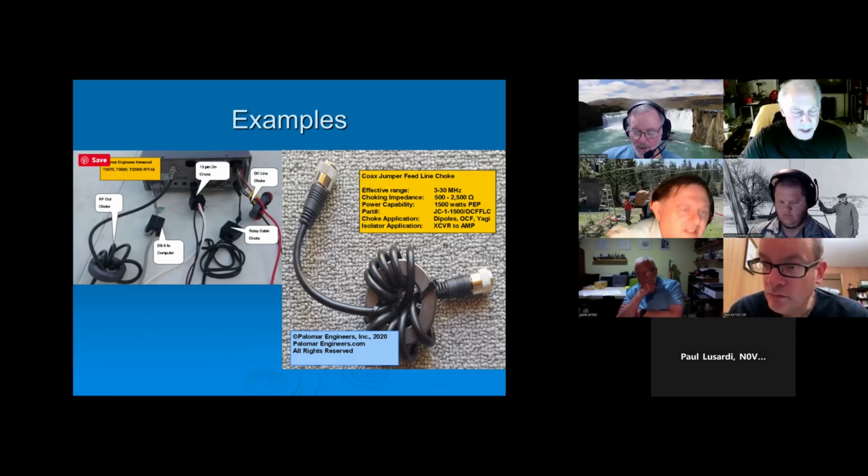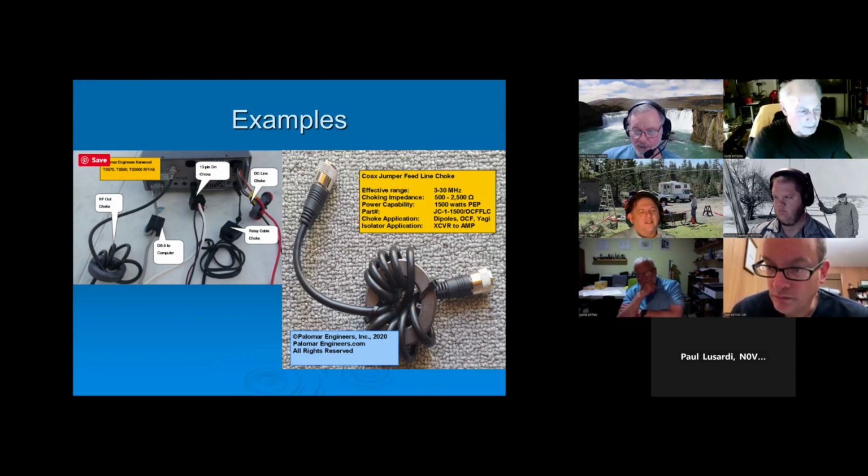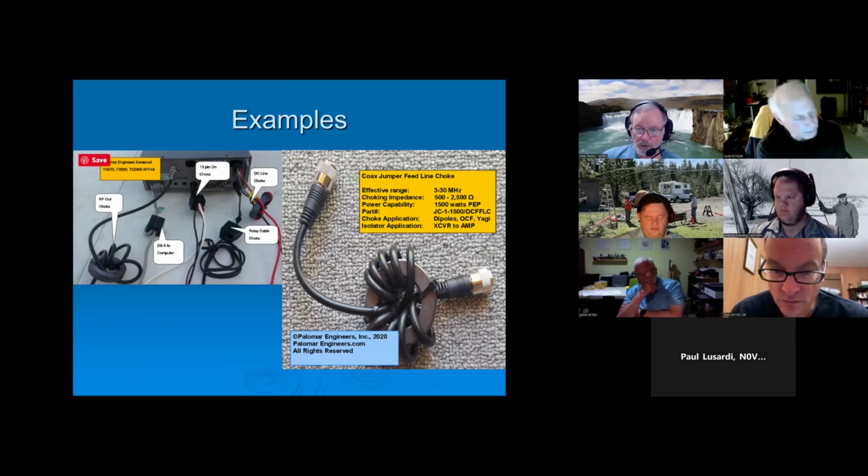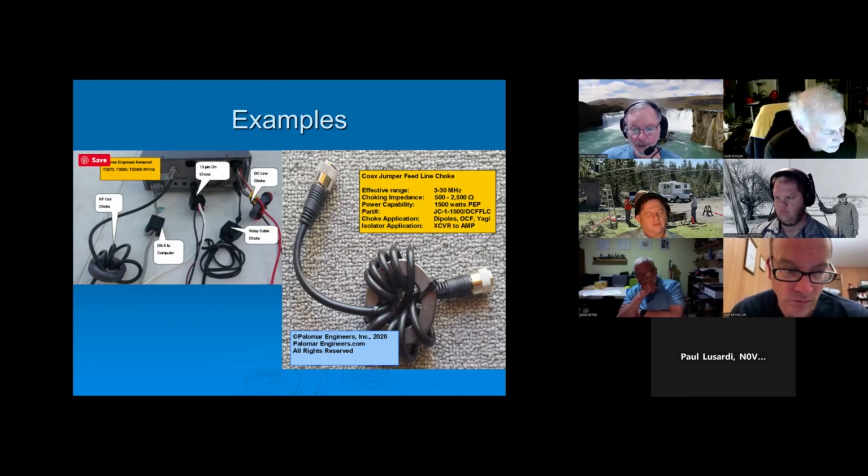Well, that's the conventional explanation you'll see in a lot of textbooks. So that outer conductor, the shielding, can both radiate and also be the source of RF energy getting coupled into that coax and then being transmitted along the outer shield.